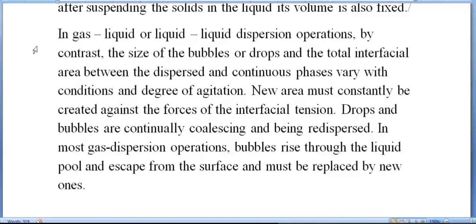Now suppose if you further close it, what will happen? The gas may not have the strength to come out because the drag force of the orifice plate is very high. So it may not overcome it, so it accumulates inside. It all depends upon how you are adjusting the valve, and by seeing into the system only, you should control the valve, and once you control it, don't disturb the valve position. Let it be as it is. Then only you will get bubbles coming out successfully from the distributor plates.